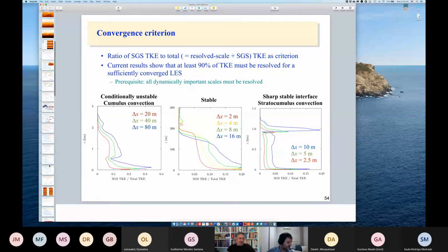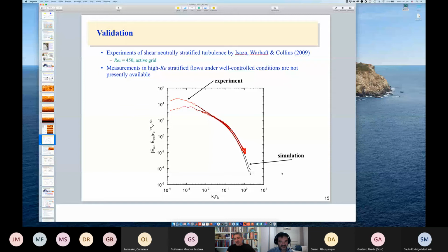But you have to remember that this is Kolmogorov scaling, so there could be a lot of scales here on the right, because this is exponential, to the k to the minus 5/3. So the integral left out is very small, but the smallest scale can be very far from your grid resolution. TKE is the integral of the spectrum, so you're left with just a tiny fraction of the integral, but the smallest length scale could be pretty far from your grid, even at 1 meter resolution in that case.